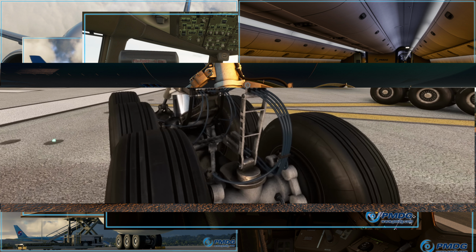Now, what's really cool is that in the real airplane there is a little switch located near the gear base that is going to enable hydraulic pressure again to the main gear doors so that they can be closed again. Unfortunately, Microsoft Flight Simulator doesn't enable click spots on the external model, so it was not possible to model that switch right in the location where it actually is. But you can use the maintenance menu in the Universal Flight Tablet or the FMC to reset the gear bay doors so that when hydraulic pressure is being applied again after an alternate gear extension, they can retract again.